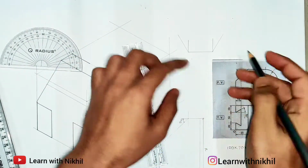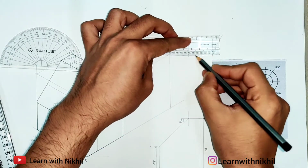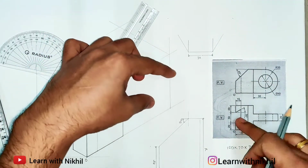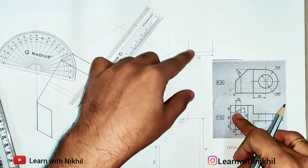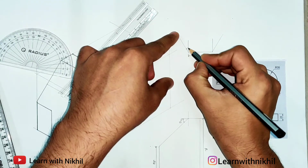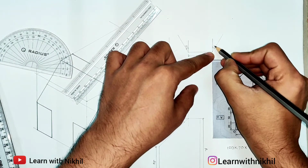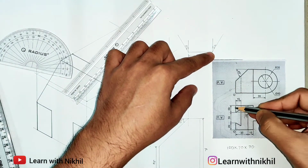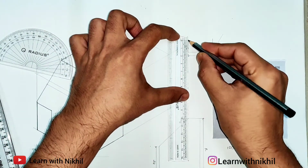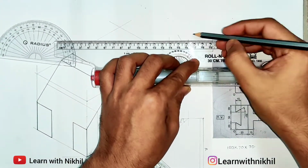So this I have drawn horizontally. This is 30 millimeter. So this is the gap. We have drawn the angle. Angles on both the sides are 30 degrees. Here also and here as well. Now this gap is 15 millimeter. So I'm just marking the point. So this is 15 millimeter gap. Now I'll draw a parallel line through it.